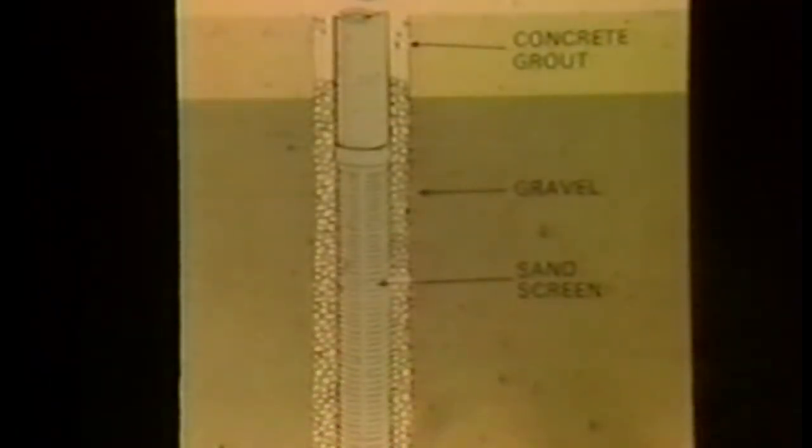The techniques used to construct a well vary and depend on drilling depths and the geologic water-bearing formations below the surface. These supply water to the well. The United States Geological Survey offices in each state and other state water agencies can furnish information on groundwater availability and drilling depths. One type of irrigation well construction is called gravel-packed well. The gravel which surrounds the well casing prevents sand from entering the well.